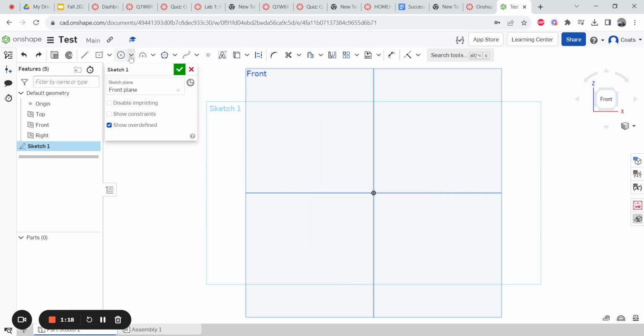Okay. Then you have your ellipse tool. Okay, it's under that drop-down menu as well. So it's like the center point circle where you're going to want to give it a center spot, and after you give it a center spot, think of this kind of like something that's oblong. See how the yellow line goes straight up? That means this is going to be a perpendicular, straight up vertical line, or horizontal right there. Okay, so if I click that, now I can click again and see how wide I want the circle to be. I mean, sorry, not wide, but just that direction. I believe that's the semi-minor axis around that ellipse. So you click it again, and that would be that.